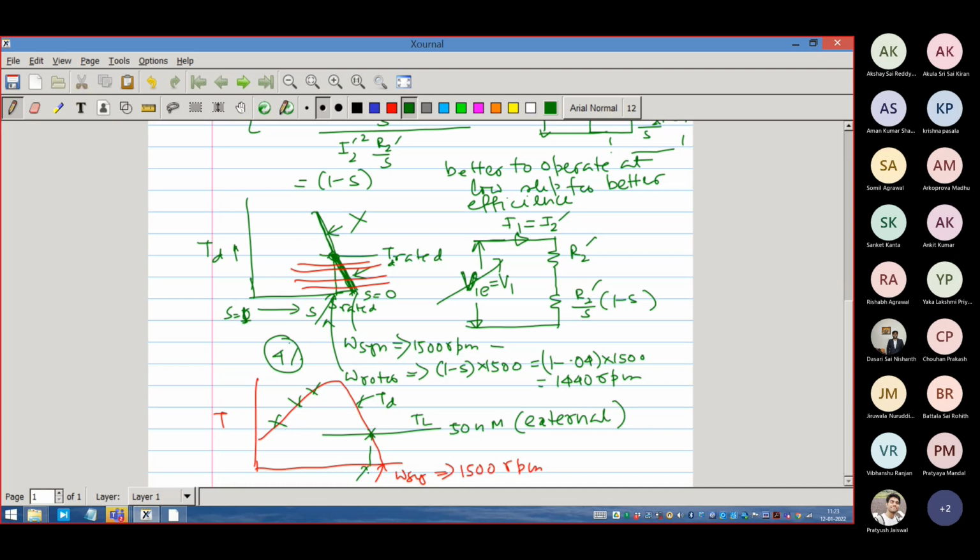So in operation, in our lab or where the supply system is not controlled, where the supply system is frozen in terms of the amount of voltage and the frequency, the external world's demand is catered to by dropping the actual speed of the machine. Synchronous speed remains unchanged. So depending upon different torques, if there is another torque level, suppose this is 25 Newton meter, we'll see how much the speed will be.